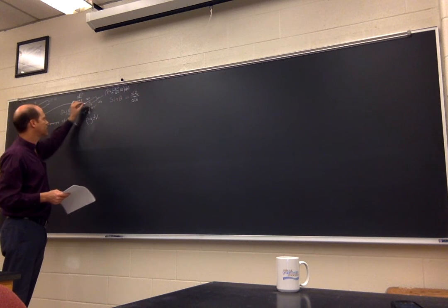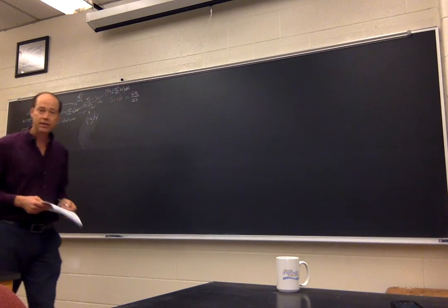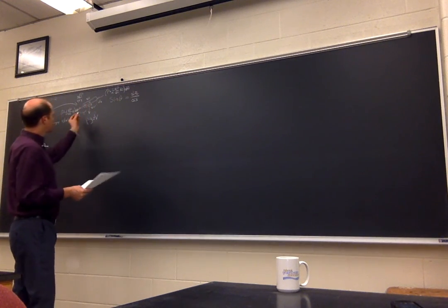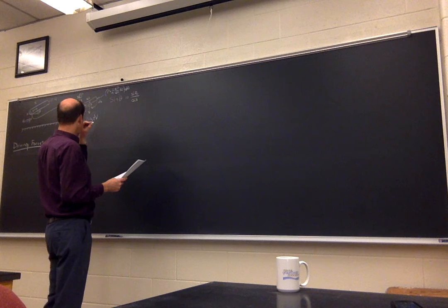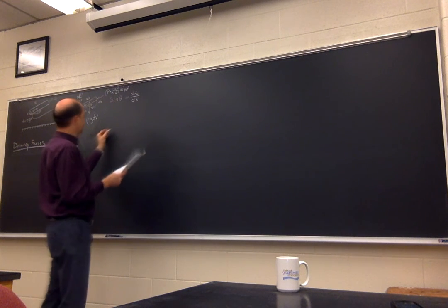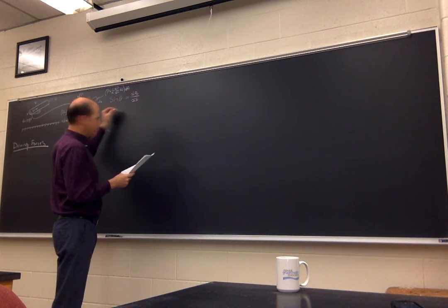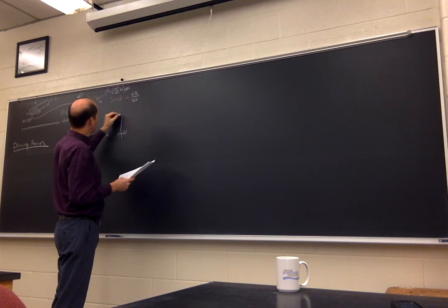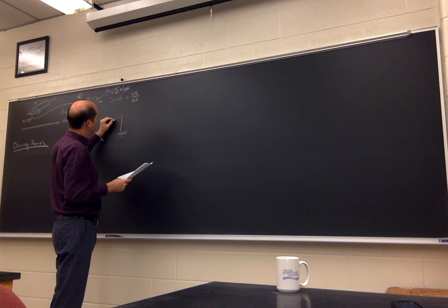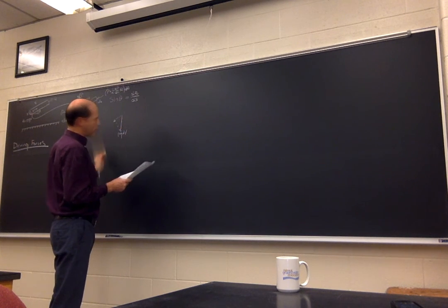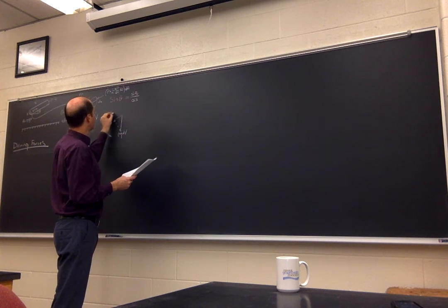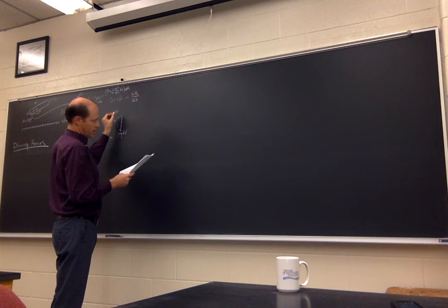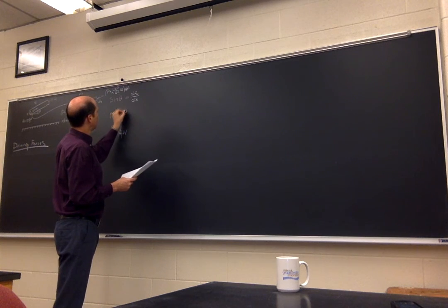In other words, it is the component of the gravitational force that is pulling the fluid back down the tube. And so assessing that, in our geometry of this problem, if this is rho g dV, then this component of the force acting down the pipe is rho g dV sine of theta.